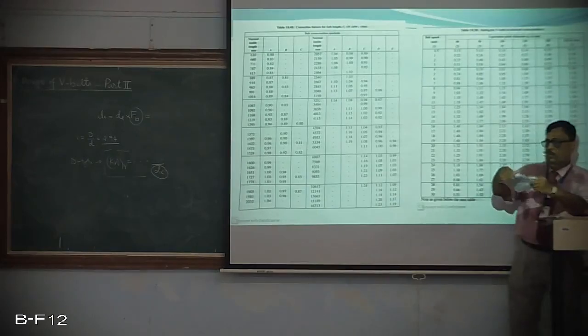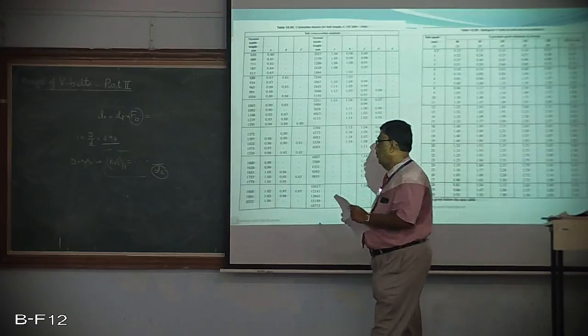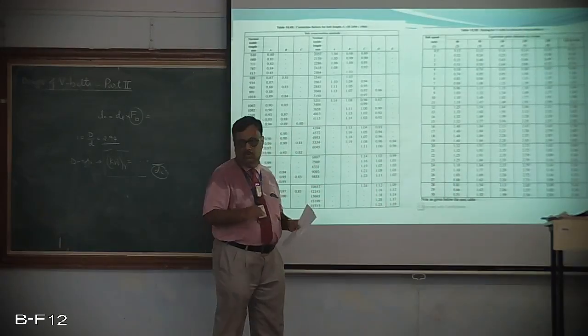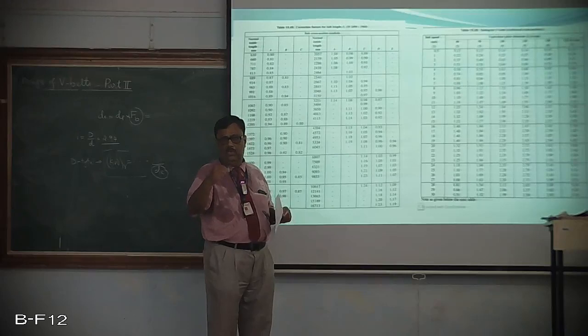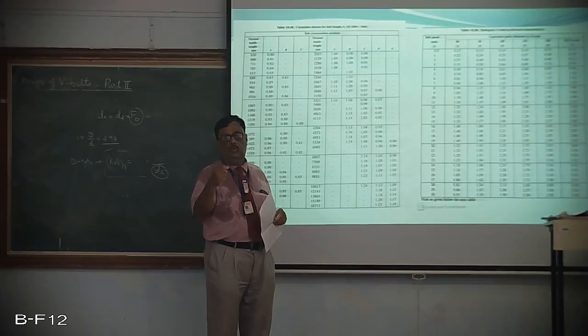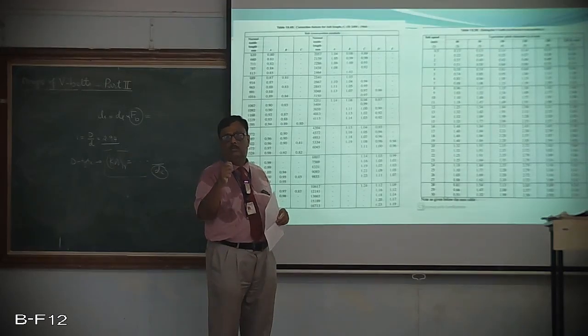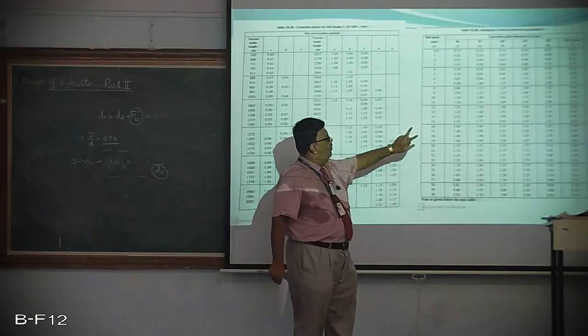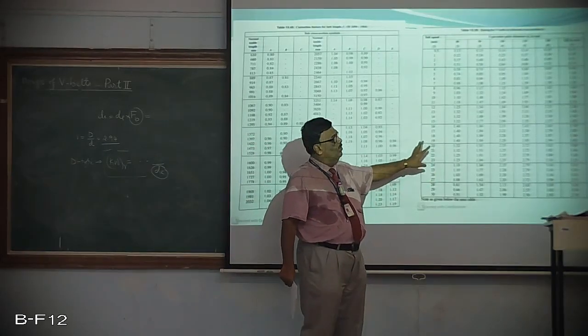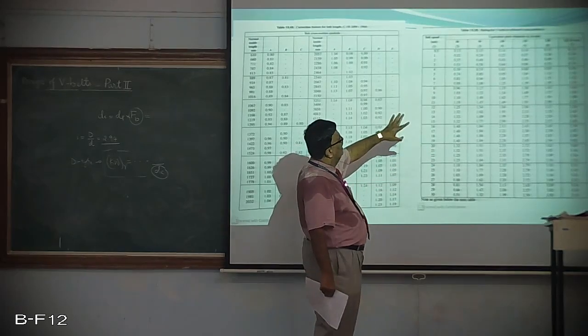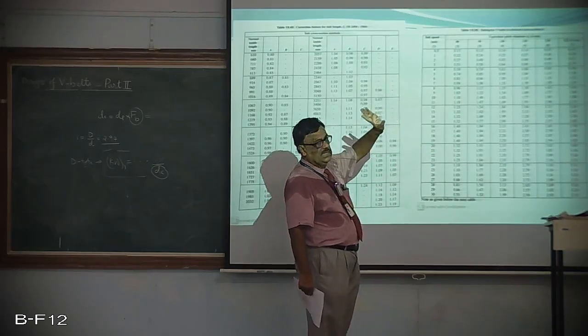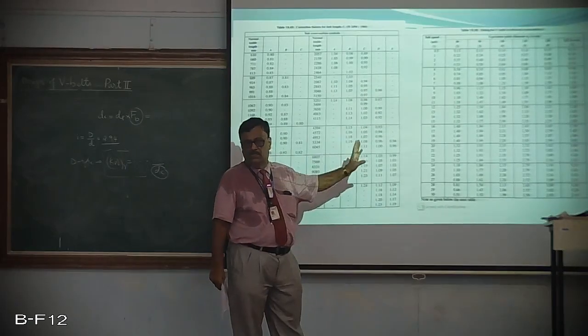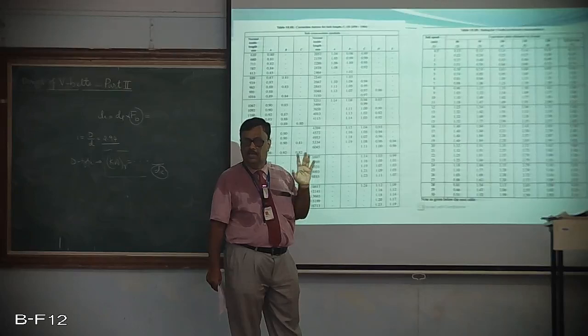See, look at this. Yesterday's problem. Imagine that you are in the field and you urgently want to know, for a particular velocity of the belt, how much power one belt of A type, B type or C type can transmit, without going through all these calculations. Therefore, in the data handbook, ready tables of this type are available. For example, look here. This table is for A belts, for cross section A. Tables of this type are available for B type, C type, D and E type also.